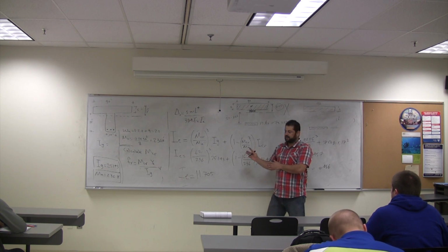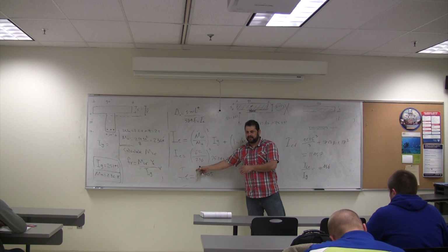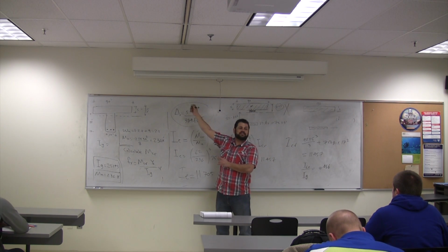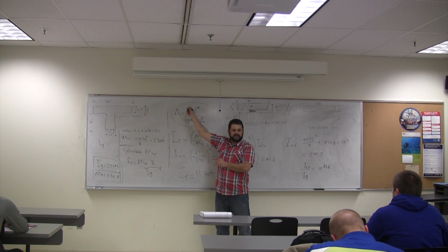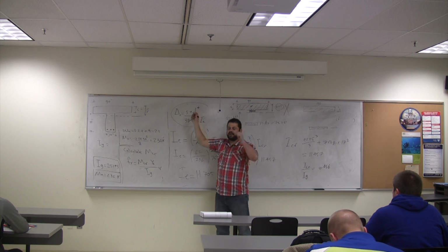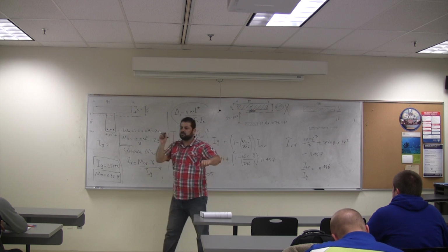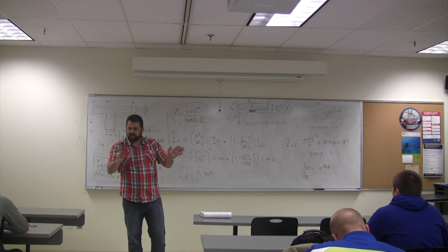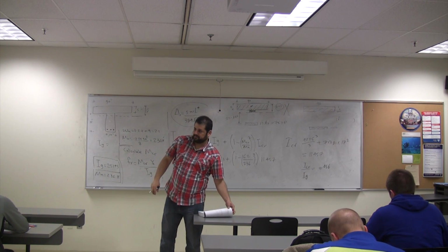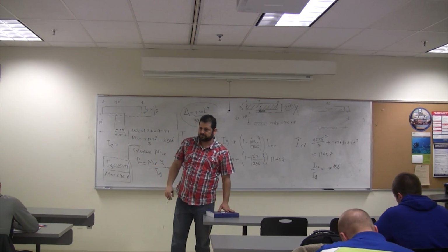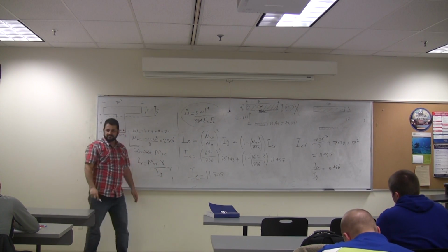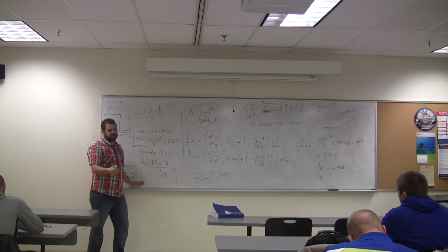Okay, guys? Now this one must be checked. Now you can calculate delta for the live load, the service live load. Check delta for me for the service live load, and go to table 7.2 and see what's the requirement of the immediate deflection due to live load, and check if they are good or not. Okay, you do this on your own. That's for sure a problem in the exam. So check it. If you have any questions, let me know.